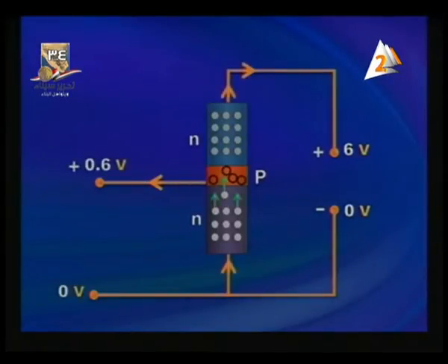But if we apply a positive potential, for example, positive 0.6 volt, on the base emitter, a current, yes, electrons will flow from the N-type emitter across the junction in the P-type. Okay, in the region of the collector, they will be attracted by the positive plate of the 6-volt battery.